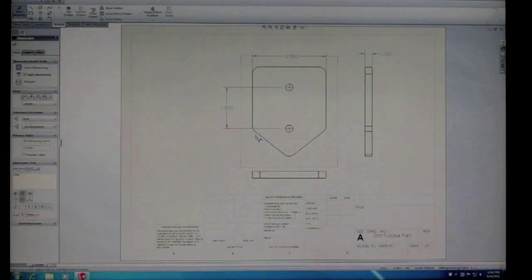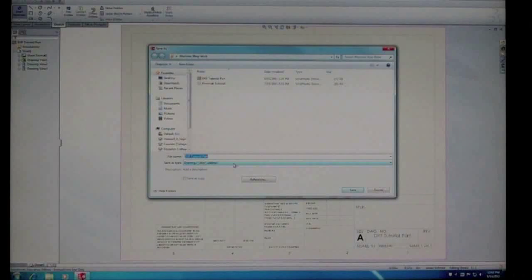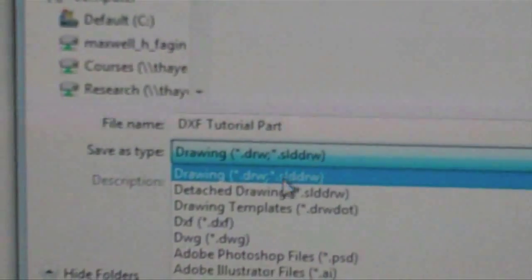To create a DXF file, open the drawing of your part in the CAD program, in this case SolidWorks. Hide any spurious dimensions and annotations, as these can cause problems with the ProtoTRAK reading of the file. Be sure that every path you want the ProtoTRAK to follow is represented in the drawing views. Then save it as a DXF file.